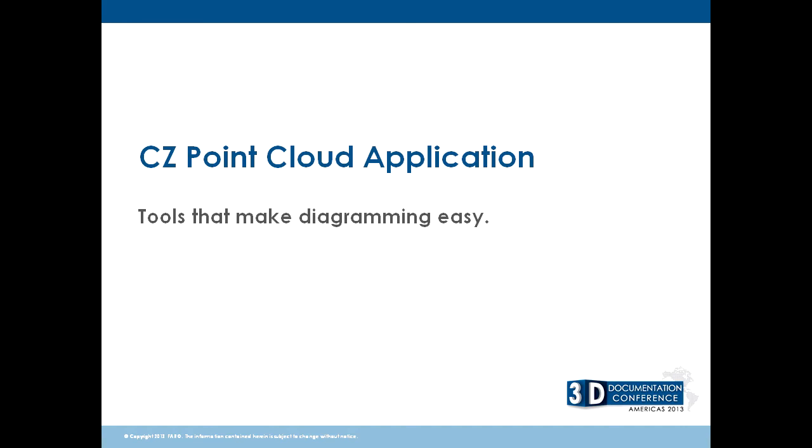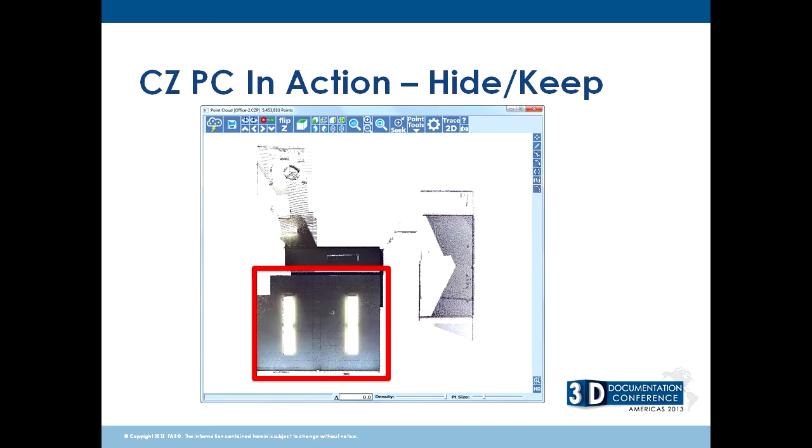What I'm going to do is show you some snapshots of what we can do and some movies of what happens, so I don't slow us down and we have time to look at this. So really quickly, this is a part of our office scanned. This is a top-down view. You can see the ceiling and the lights. And so we can quickly clean this up. If you didn't do this cleanup in your processing software, we can do it in here.